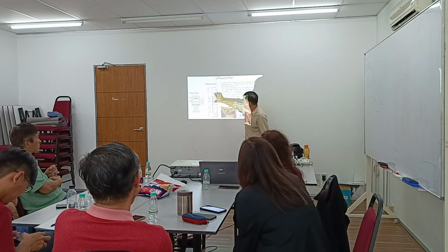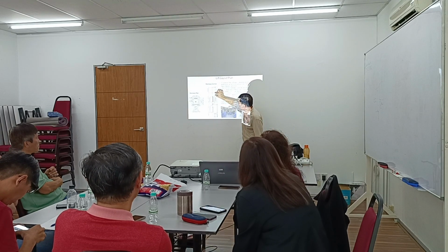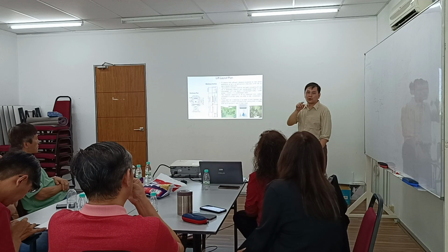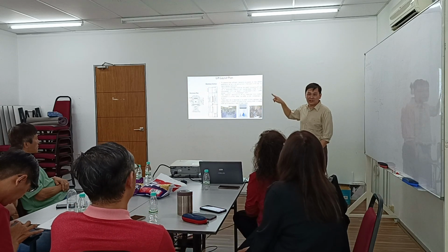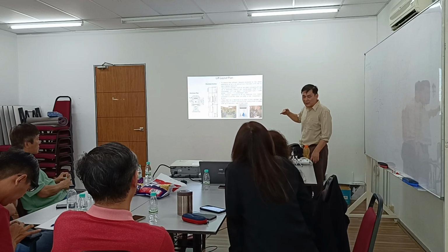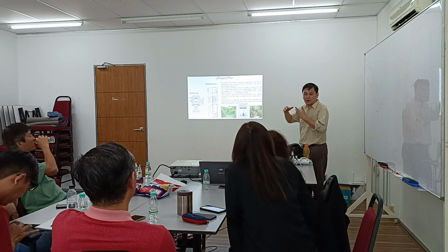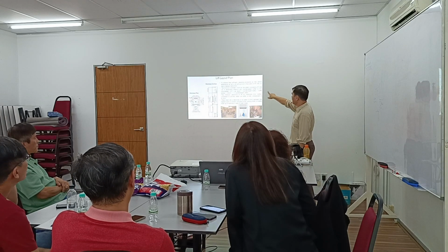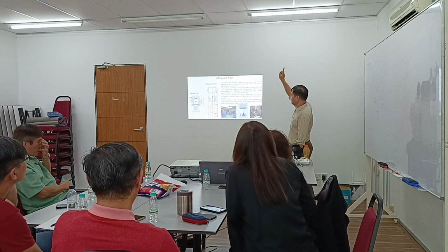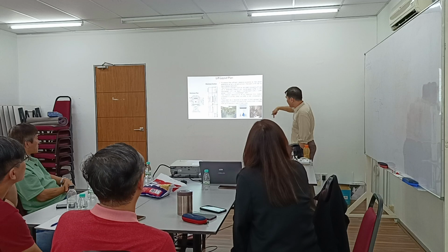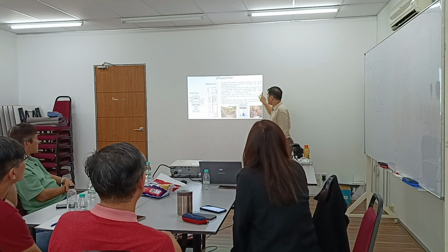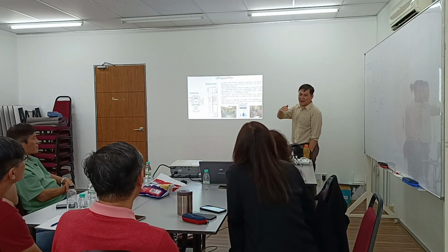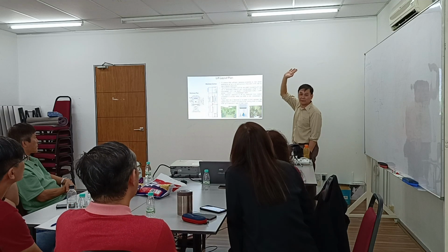So this is the overhead, the highest floor, and then they need to ensure there is sufficient clearance top and bottom. The purpose of having clearance is actually to protect the people, the maintenance people or installation people, so that in the event the lift overruns, the people are still protected, not crushed. The minimum overhead can be calculated by considering lift overrun in the ascending direction and the counterweight buffer compressed, then you add this one, this one, this one. That will be the overhead required. So that's why the higher the lift, the higher the overhead.